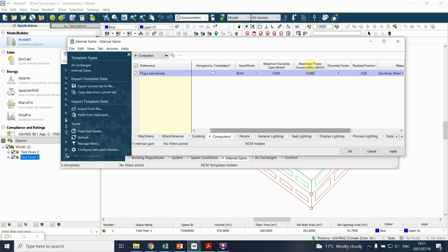Then what you can define, and this is not necessary, I often don't define it, but you can decide that, you know what, I am going to assume that 100% of the energy used gets translated into sensible heat gain. That's not really accurate, especially not for equipment, because the laptops you use don't generate as much heat as the amount of electricity they use. But if you are designing a kitchen, for instance, you might start saying, okay, wait a minute, there's quite a lot of heat generated. I might actually want to adjust that in the end.